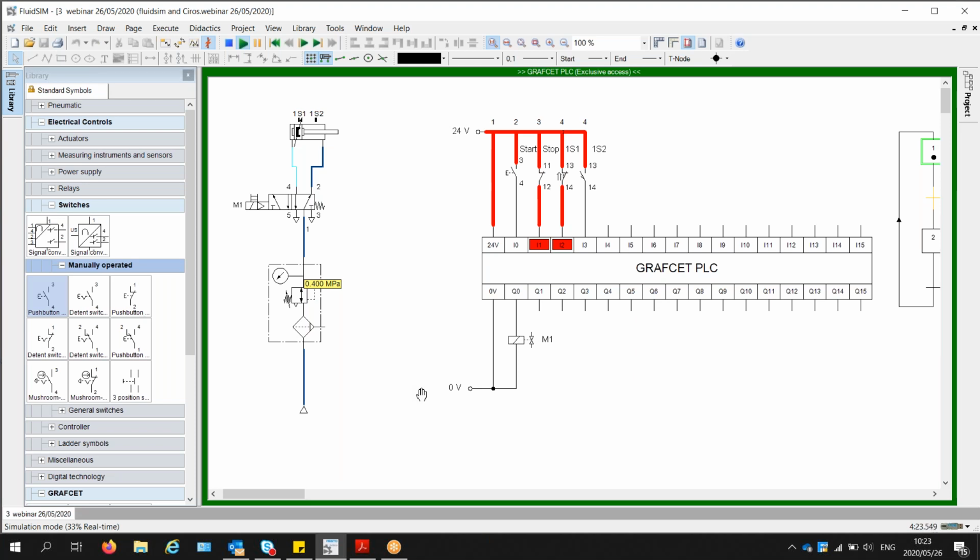This is an application, Easy OPC, that allows communication between the different Festo software such as Fluidsim and Codesys or TIA Portal. So you can take your TIA Portal, your Siemens, and you can speak straight into Fluidsim through Easy OPC. You can run Easy OPC at the same time as you're running Fluidsim.